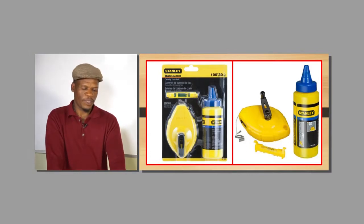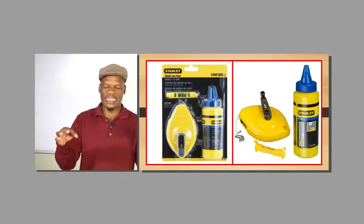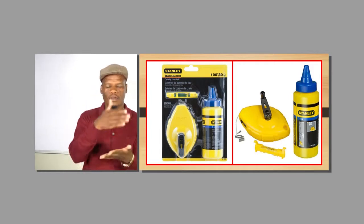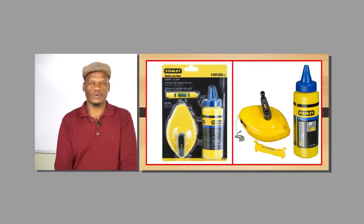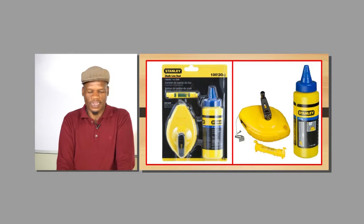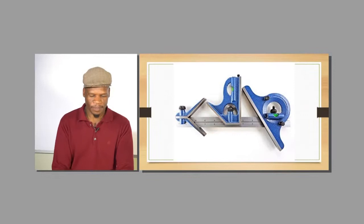Then the first one is going to be your chalk line. Your chalk line is normally used to strike a line on the material. If you have to cut the material, then you can use it. If you don't want to draw a line using the pencil and a ruler, you can use the chalk line and then you strike the line. So just take note, the chalk line doesn't draw a line, it strikes the line into the material. And you can see that person there is using the chalk line just to mark off that line on the materials, which is referred to as striking of the line.